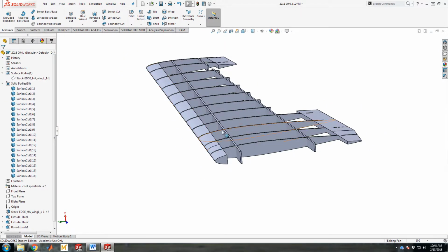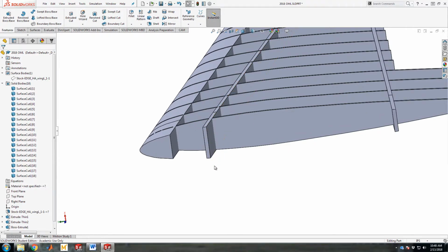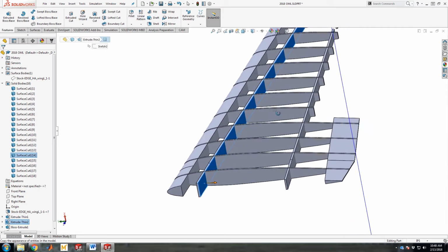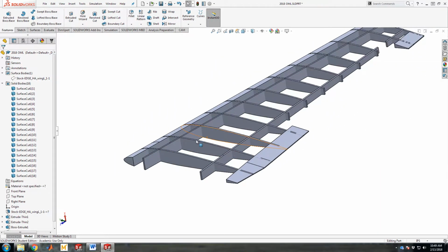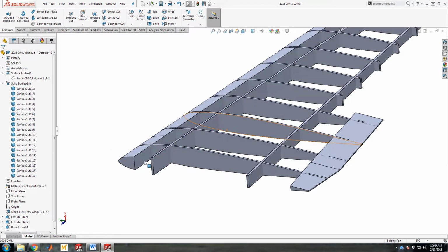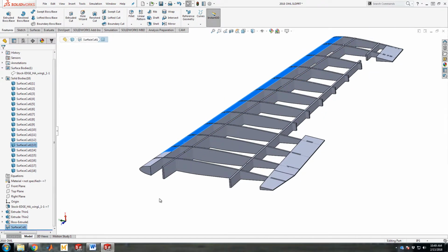But each one of these parts is isolated. It would be nice at this point if you could essentially make a slot for your shear web to remain uninterrupted. The ribs are by far a much more lightly loaded structure than the actual main spar. In fact, the leading edge stock you may not want to be terribly structural either, or maybe that also becomes your main spar. Your choice, your design, whatever. That could be foam for all I know.